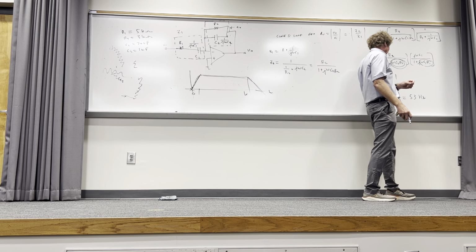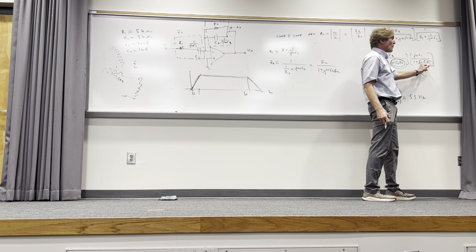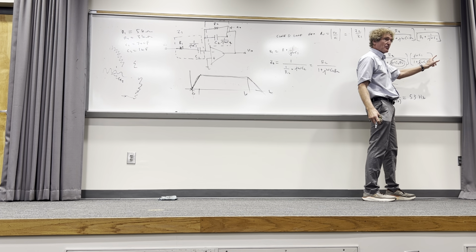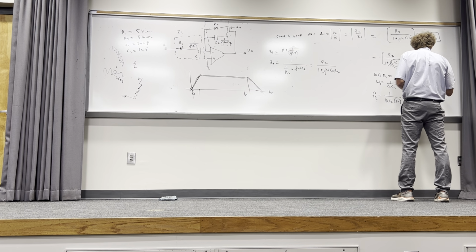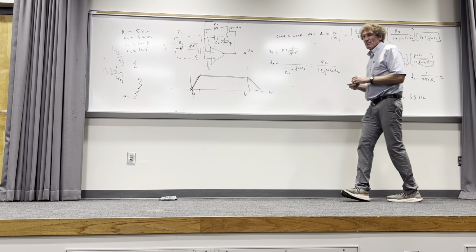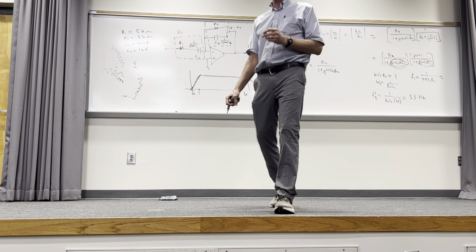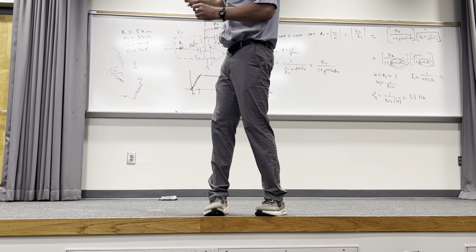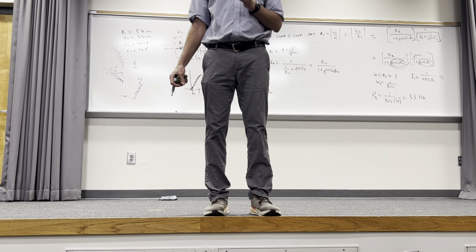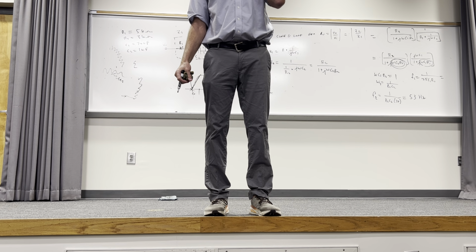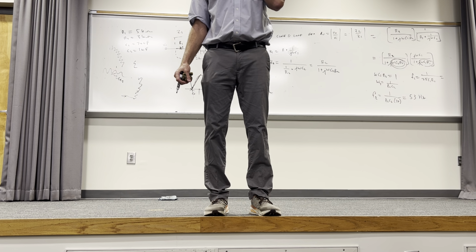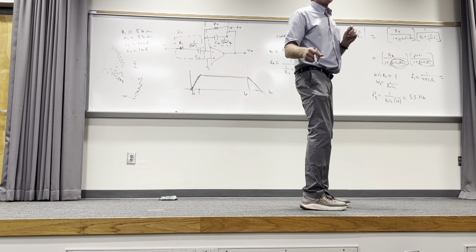Now, I might as well just say, if you look here, can everybody see over here, that frequency, which I'll call F1, would be 1 over C1 R1 divided by 2 pi. I'm going to just put it here. I need these values. So this is going to be 1 over 2 pi, and this is going to be C1 R1. All right, let's try the old mathematics again. Let's get past basic math. What's that value based on those values, or your book's values? Maybe you can't read my writing, is the problem. 1.59. 1.59? Wow, that's really low. Is that right? Okay.